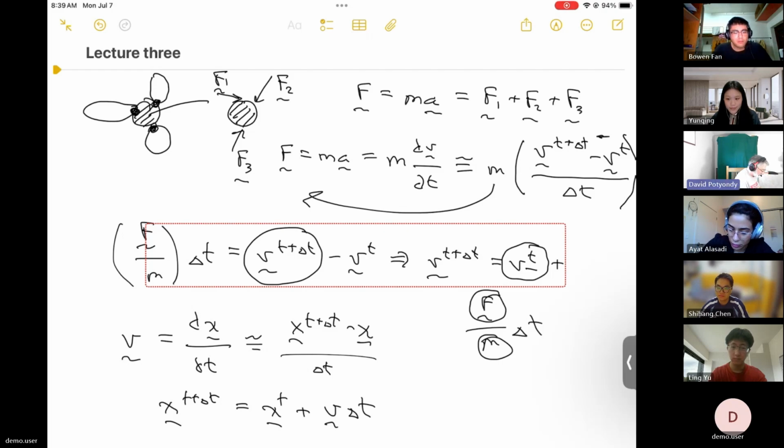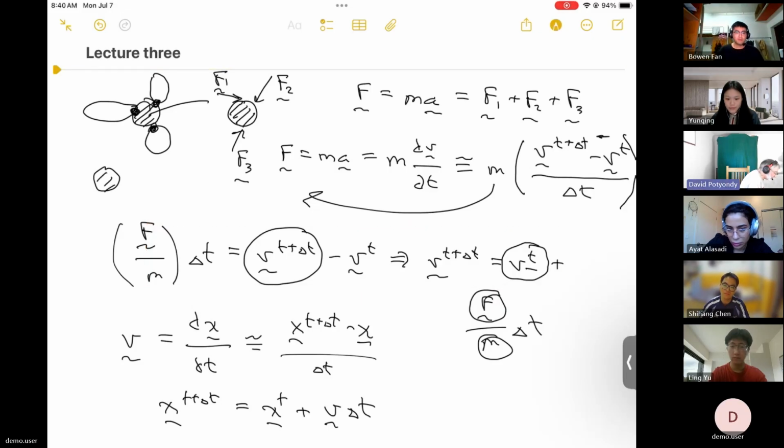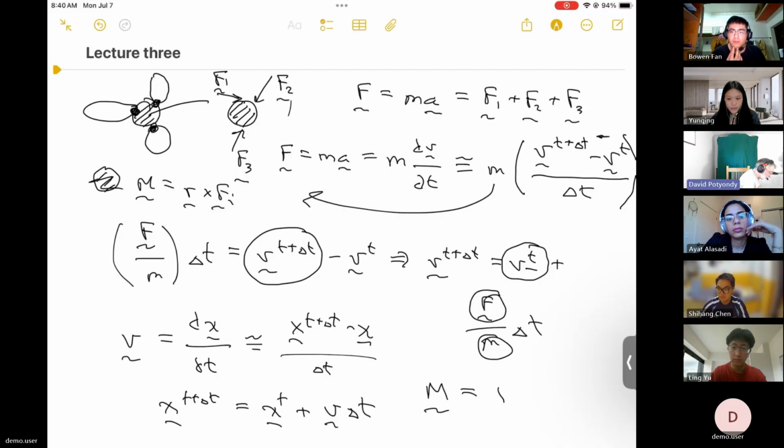Because we have a general system with 6 degrees of freedom, we not only have forces, but also remember there could be a resultant moment. The total moment on that particle is r cross Fi, where r is the radius of the particle. So I can also get a resultant moment. And the Newton law for rigid body dynamics is the total resultant moment equals I times omega dot.